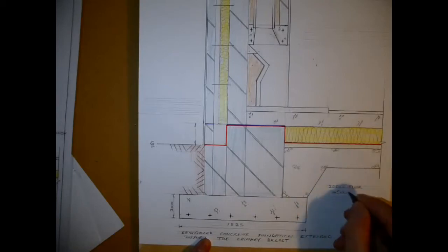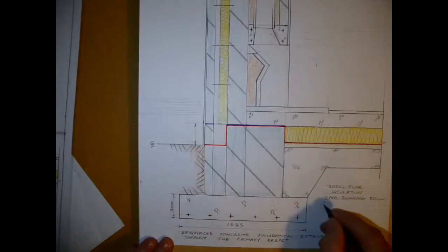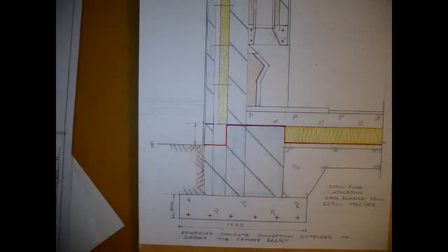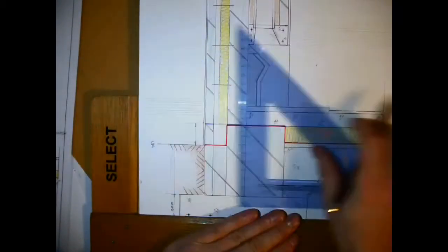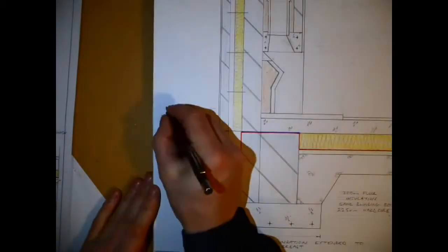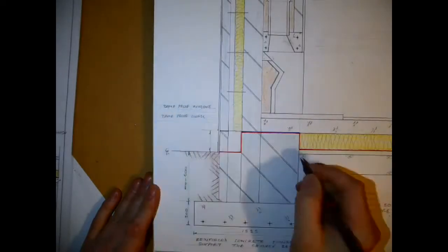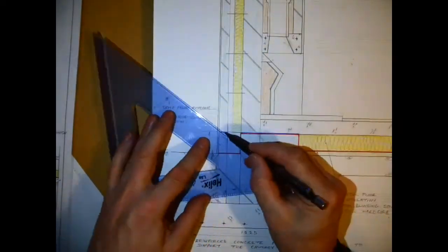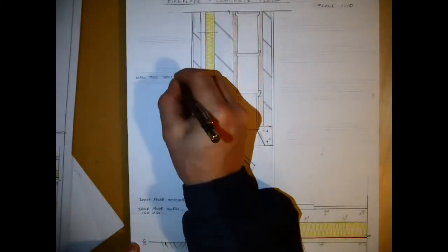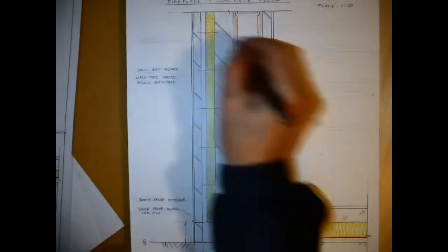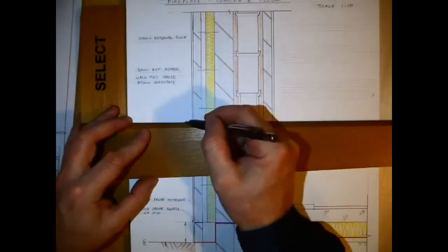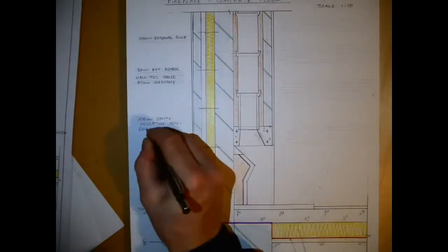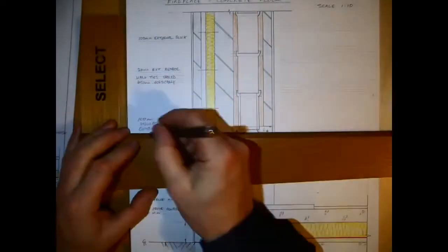1525 is the size that I have shown here, but you could change that around. I've gone for a 225 millimeter block on the internal, so that it allows for less likelihood of temperature transfer into the block and maybe cracking it or the likes. And use guidelines for all your details that are shown in here. There's a tremendous amount of details that are shown in this here.